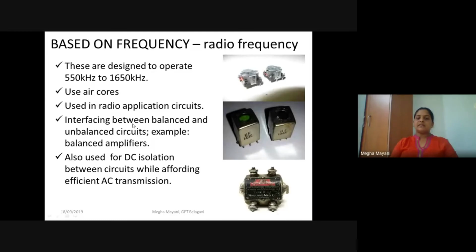And these are acting like the interfaces between balanced and unbalanced circuits. Like we have balanced amplifiers, so these transformers are widely used in balanced type of amplifiers. And these provide a DC isolation between the circuits with good efficiency. So some images for radio frequency transformers have been put up here. You can give a look.